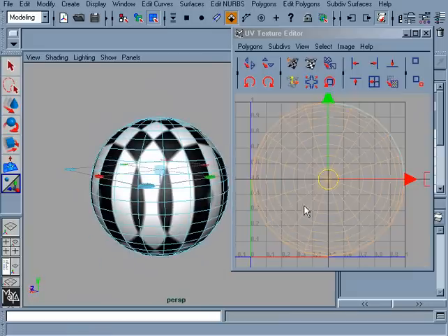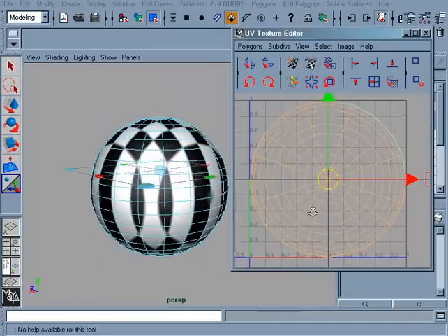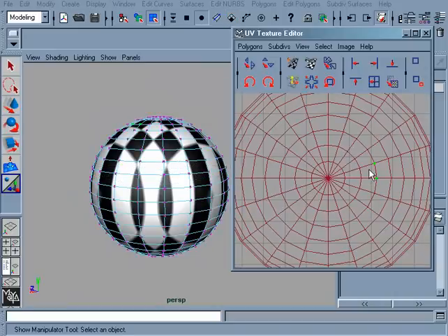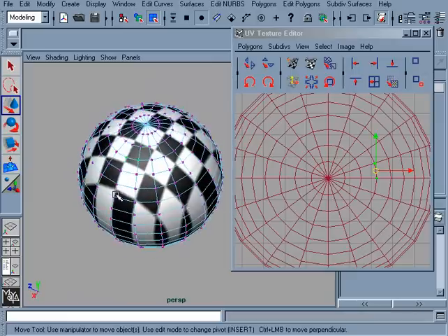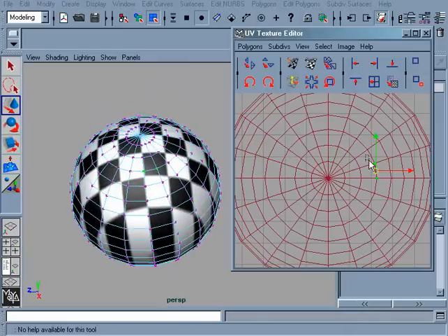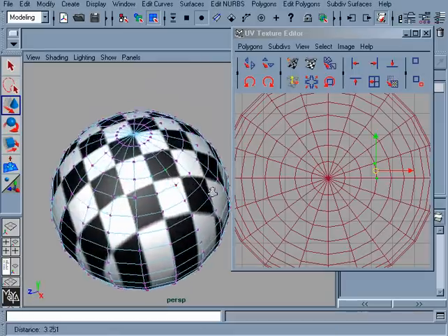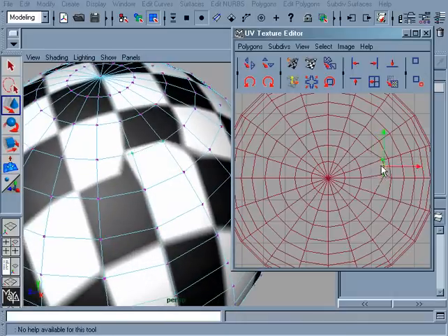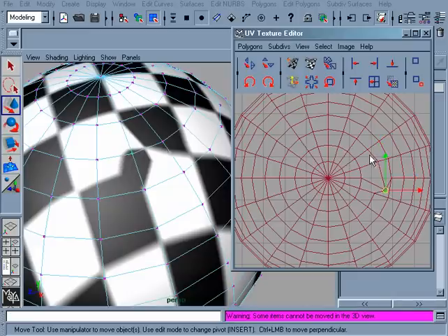And again, you can see in the UV layout exactly what this projection looks like. So you can always grab these UVs if you wanted to in order to make subtle changes. So if I were to grab, let's say, these UVs, you can see here they are on the model. And I could always move these around to adjust how this texture is going to flow. If I ever needed to make any subtle changes to this, we have that ability.